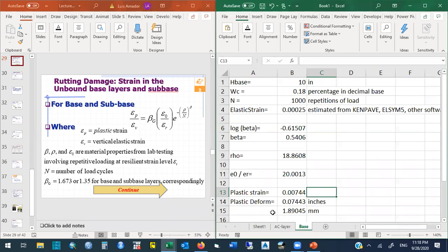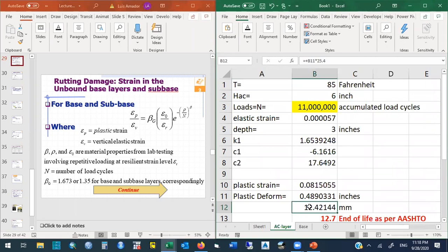So if this is part of the same pavement system, when the base goes down because it suffers a deformation, the asphalt will go that amount as well, plus the deformation of the asphalt. I'm not sure I'm illustrating myself. I have hot mix asphalt and I have the base. The base goes down this amount. The asphalt automatically goes down that amount because it's supported directly over the base. But the asphalt is also going down whatever this amount happens to be.